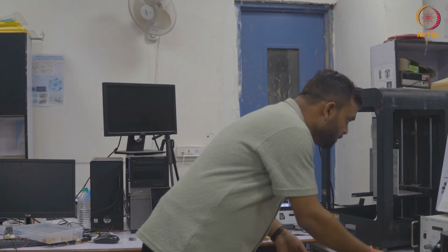Another application is that we have developed an IoT module, where our TNG is used as a sensor on machine tool monitoring. Let's suppose we have some pretty old machines, and we don't know when they will fail. We can attach this triboelectric nanogenerator on the machine tools. Based on the vibration, it will generate some amount of voltage and current signals, and we can analyze those signals to predict maintenance of the machine tools.